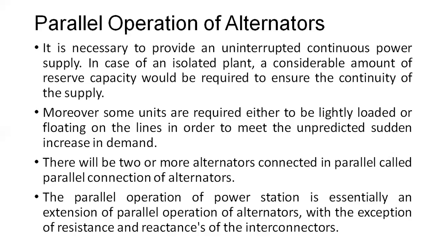In case of an isolated plant, a considerable amount of reserve capacity would be required to ensure the continuity of the supply. Moreover, some units are required either to be lightly loaded or floating on the lines in order to meet the unpredicted sudden increase in demand. That is a very important point.